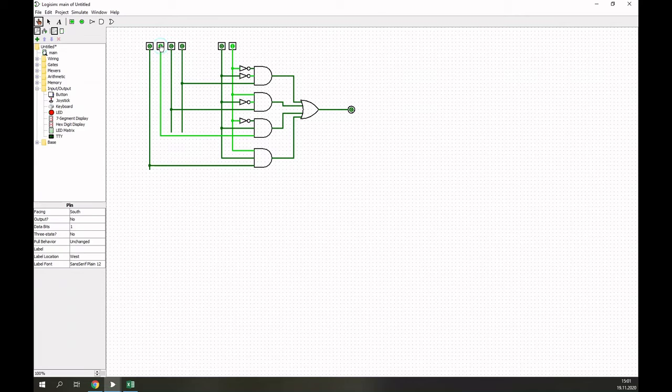So I select the second line. So you see, if I switch on this, I select this line, so I can change this. If I change this, it will appear in the output, and all of the others are not influenced. And only if I have both selected, I will select the fourth line. So it means with this control address or control word, I address the other 4 input pins, so that only those value is sent to the output which I have selected with my address here.